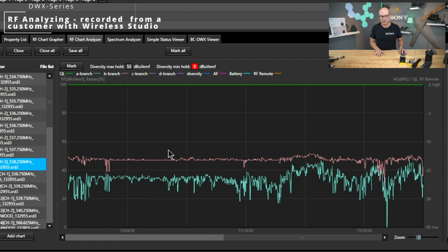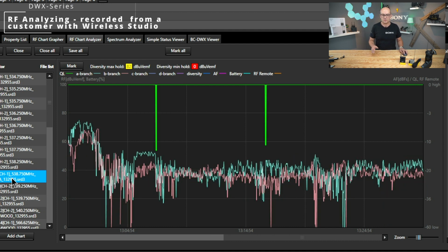Here I think maybe the body pack was not moved over a long time. But again, one antenna is, here it is more than 10 dB, so 15 to 20 dB lower the whole time where the body pack was used. I don't know what's going on with the antenna system, so something is not perfect here. Here again, the system was moved on stage, antenna level varies in a wide range, that's okay, and then we have 2 drops, which I guess one is audible, the other not.